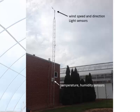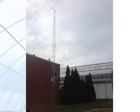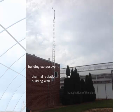Okay, it is challenging to suggest any improvement without a better understanding of the surroundings of the weather station. Here is what I found. First, the temperature and humidity sensors are not that far from the building's exhaust vent. Second, the sensors are also adjacent to the building wall that may have influences on sensor readings. Third, there are trees near the sensors. Transpiration of the plants may affect sensor readings too.